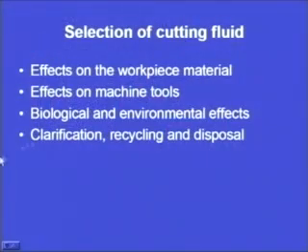Now, coming on to the selection of the cutting fluid. The selection depends upon a number of parameters. These parameters are, first, how the cutting fluid is going to affect the workpiece material, because we want that environmental attack should not take place on the workpiece material. It should form a thin layer around the workpiece when it is in the heated condition. So, how the cutting fluid affects the workpiece material is one important factor.